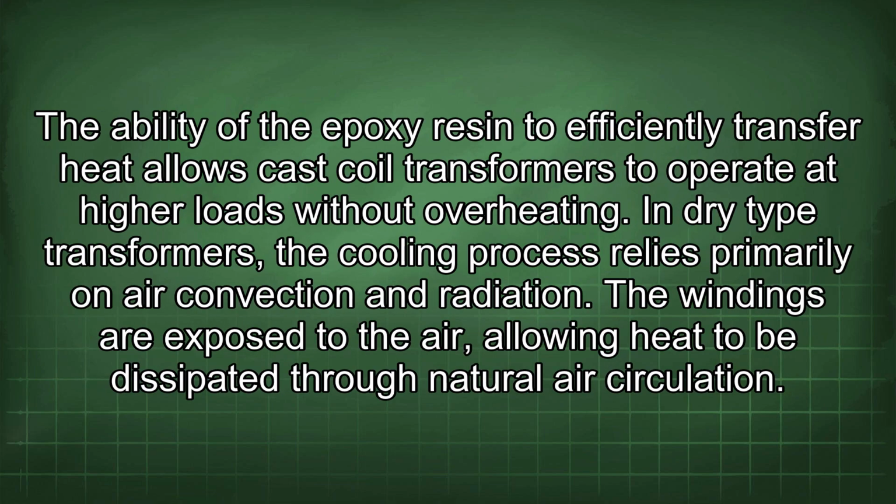The ability of the epoxy resin to efficiently transfer heat allows cast coil transformers to operate at higher loads without overheating. In dry-type transformers, the cooling process relies primarily on air convection and radiation. The windings are exposed to the air, allowing heat to be dissipated through natural air circulation.